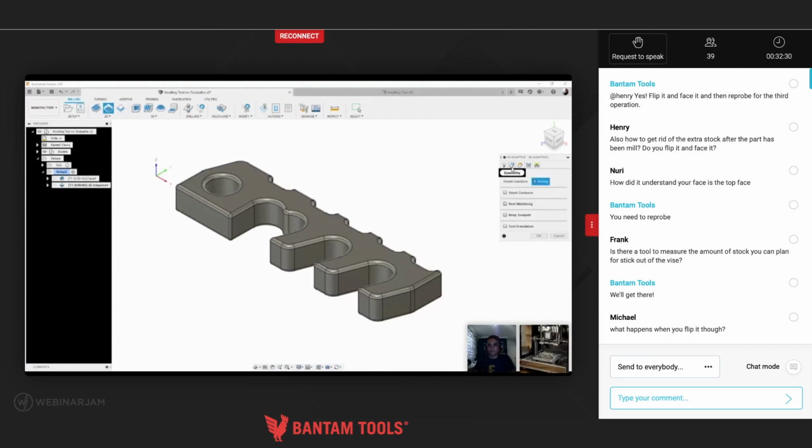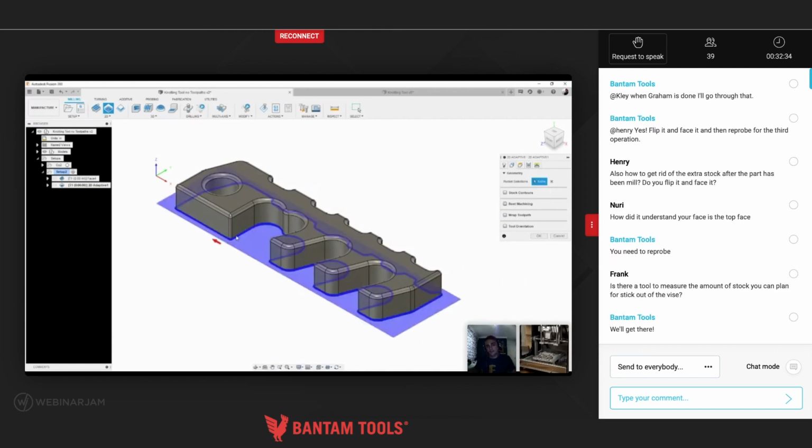Then I can go to the geometry tab. With my pocket selections, I'm going to select this edge here. You can see it's given this ghosted blue outline. What that means is it's going to machine into these blue areas, and that's denoted by this red arrow. If I press this red arrow here, it will actually machine inside this part, because what it sees is the boundary. Obviously we don't want this, so we want to make sure it's in the right place. However, this is not the depth of our toolpath.